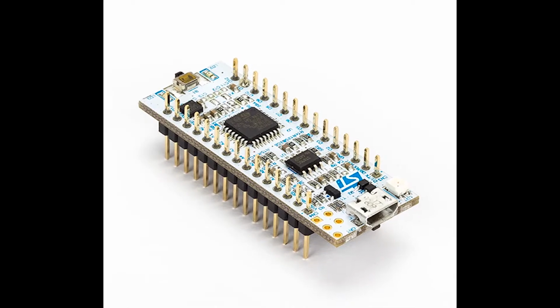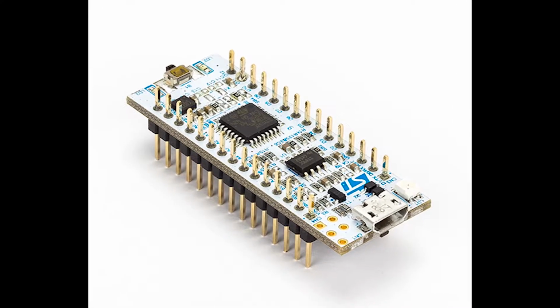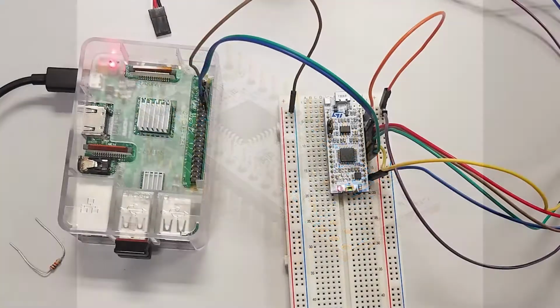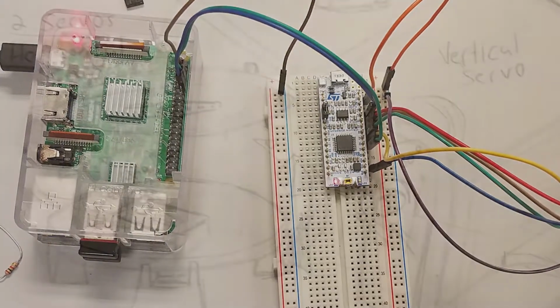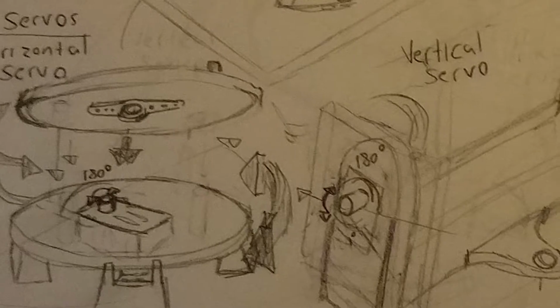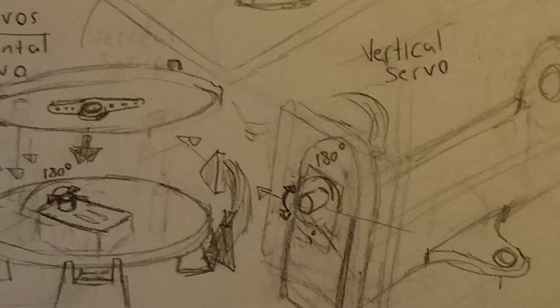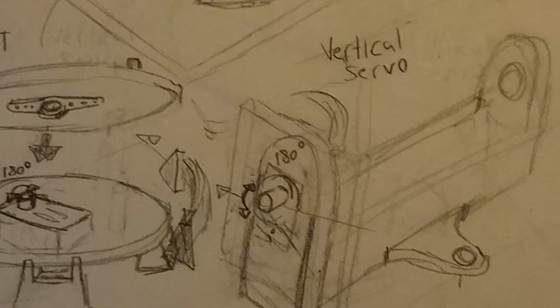The devices we will use are the STM32 Nucleo board, as well as a Raspberry Pi that will communicate to the Nucleo board using UART. Commands will then be received by two servos, one controlling the x-axis and one controlling the y-axis of the apparatus.